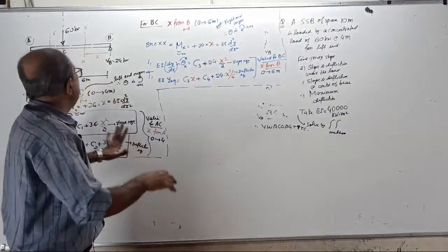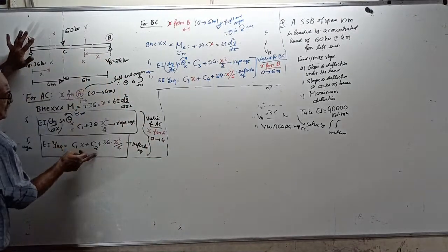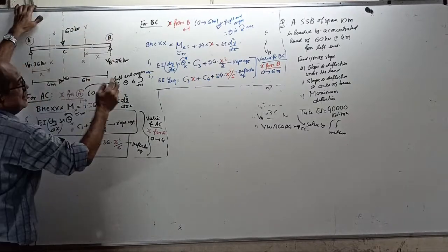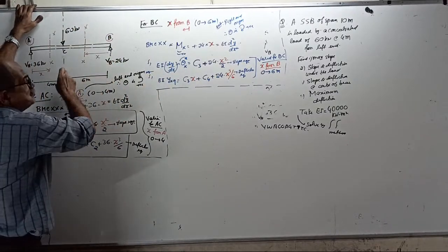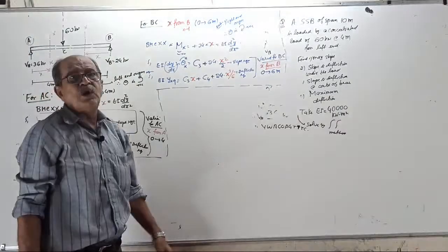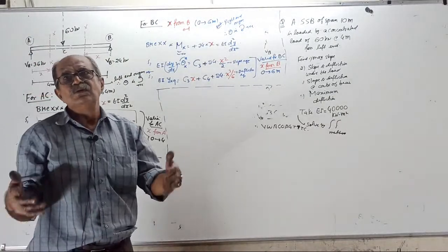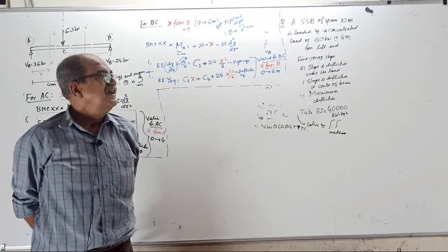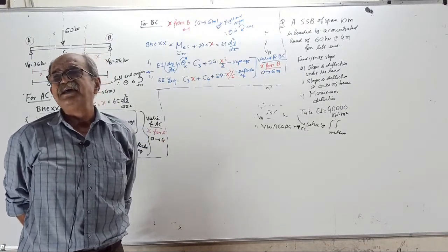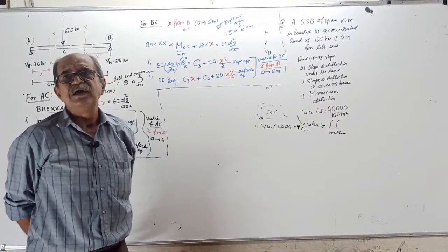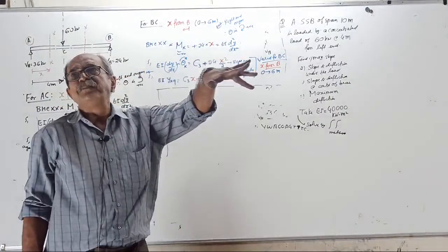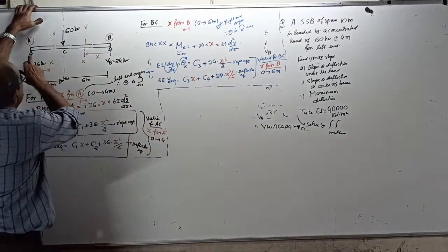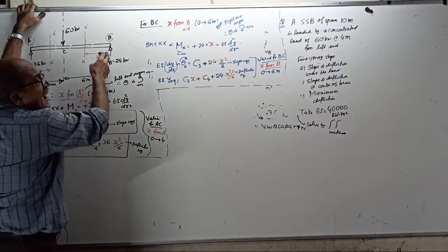Then anything you want for AC, use the first equation from 0 to 4. Anything you want on BC, use the second equation, 0 to 6. Suppose one more point load is there. Oh, you are gone, correct? Gone case then. That's why the double integration method is not preferred when there is a change of loading, or when there are standard points in between the ends.